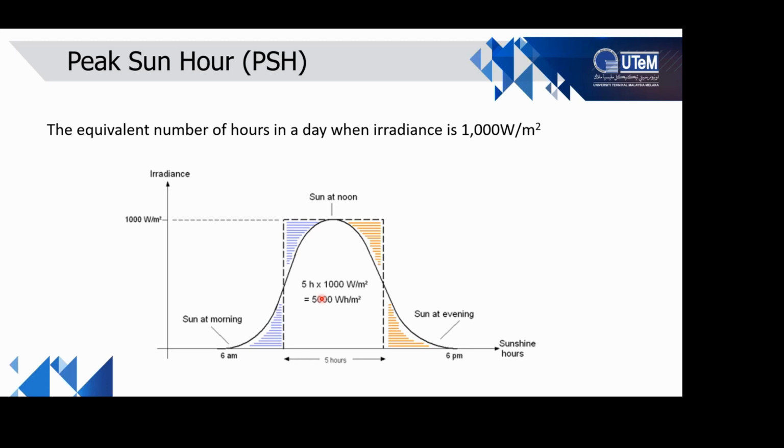So question number 3, can we design different module orientations? Landscape, portrait, sure, we can design different module orientations. Any effect related to power? No. Our orientation, whether landscape or portrait, basically has no significant effect on power. Maybe if there is an effect, it is very negligible.